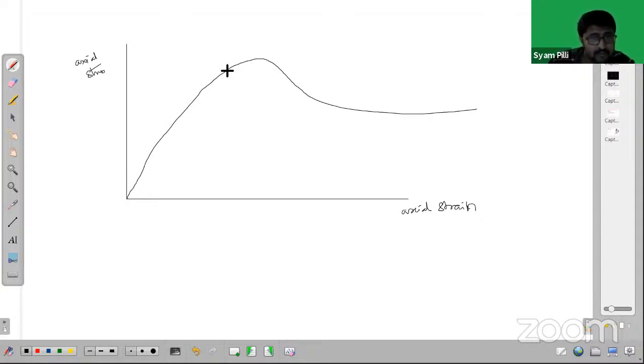So the shear strength will be much higher at the lower strains, you know. But beyond some strain, the shear strength will keep on dropping, right? So this is happening because of the dilation. We'll explain this dilation few moments after, right? So dilation means because it's a clay, so generally the dilation will not happen, but the equivalent of dilation is the negative pore water pressure, you know. So pore water pressure will get negative. So that's why all of a sudden this happens in this way, you know.